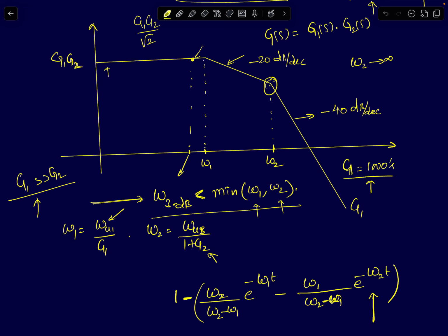So as a circuit designer, if let's say you are an IC designer who's designing the instrumentation amplifier, then you have to ensure the first stage's UGB is really good, especially for high gain settings. Generally, what does high gain mean? High gain means the feedback factor becomes very small. If the feedback factor becomes very small, then the 3 dB bandwidth also becomes smaller for these amplifiers. That's all this means. As far as a circuit designer is concerned, who's going to design a differential instrumentation amplifier, he has to take care of the first stage amplifier very well. That is what is going to contribute to the speed. So that has to have a high UGB, especially if you want to have a high gain.